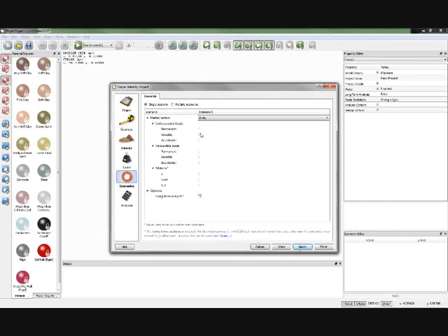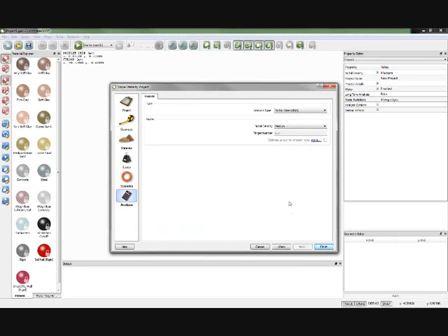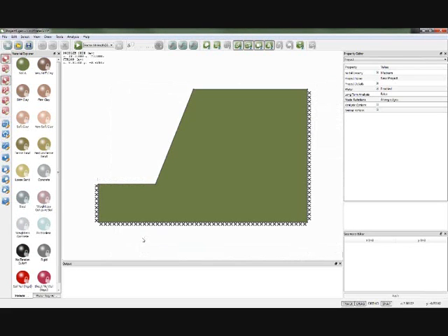You can define partial factors. We'll leave those all as 1, but you can enter Eurocode partial factors. And we can define an analysis type and a nodal density. I'll come back to those shortly. So I'll just click Finish, and then we have a very simple geometry, a very steep slope, and it's an undrained material.